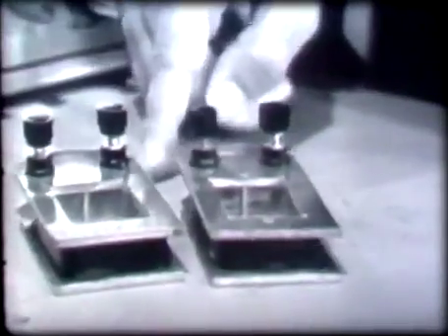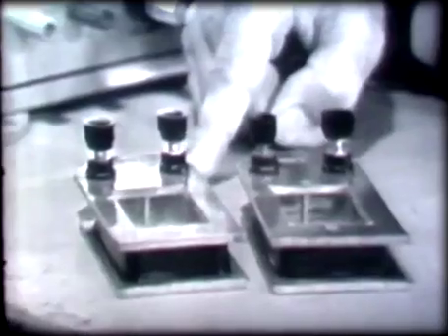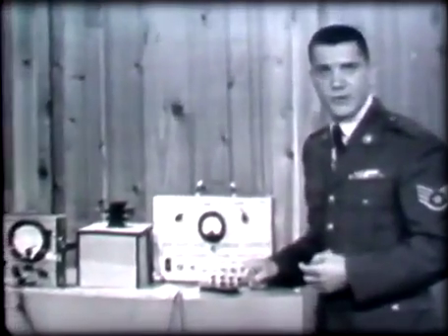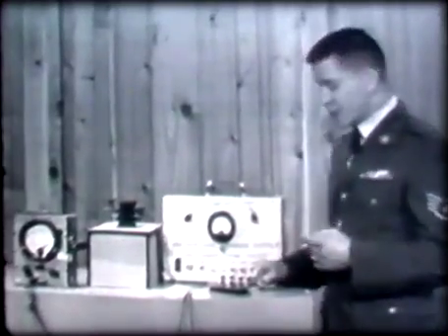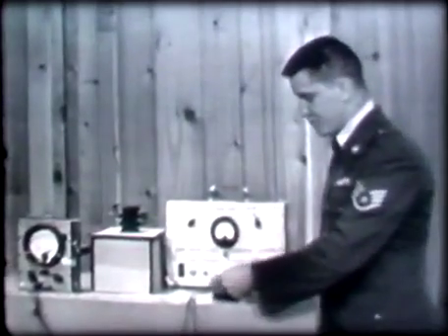The big difference in these 2 windings, however, is that one of them is shorted and one of them is open. So let's use our ohm meter and see if we can tell which is which. Remember, PSM6 has already been set up to read resistance on the ohms times 1 scale. So let's go ahead and check the resistance of the 150 turn winding first.